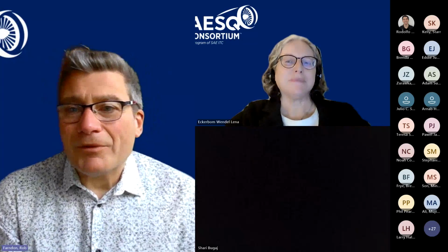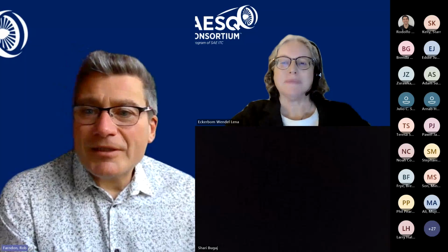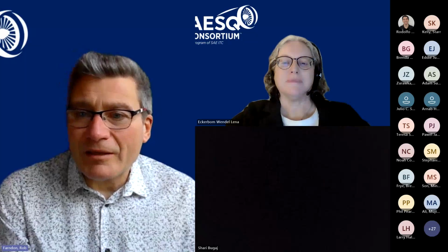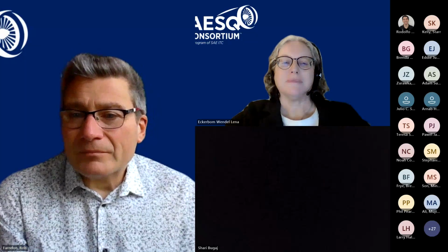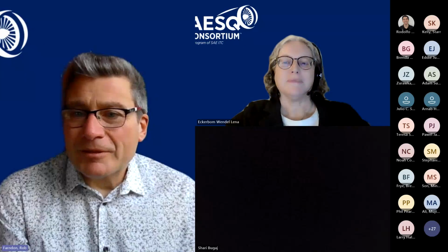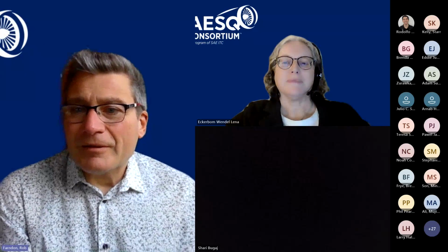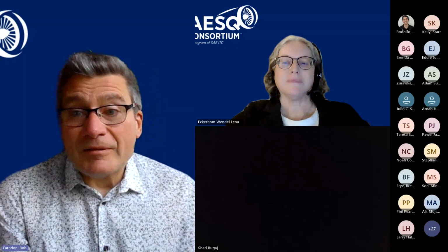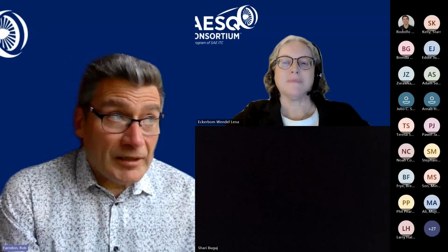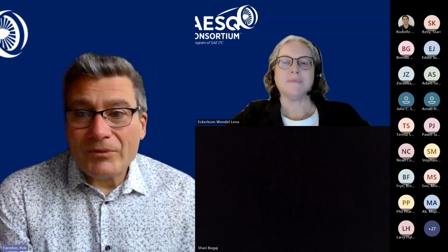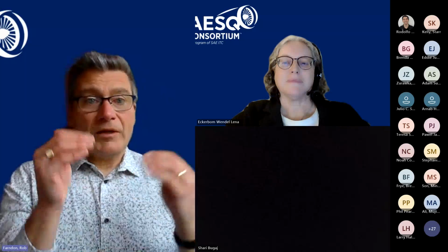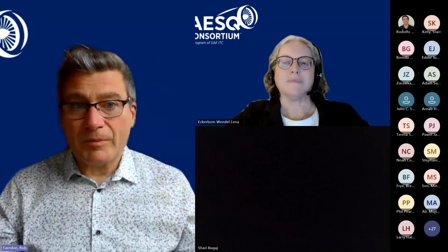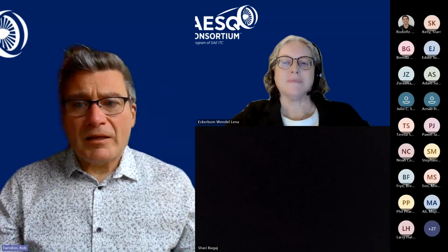Okay. There is another question come in, which is, can you go into a little more detail about how FMECA evaluates safety compared to the rating scale FMEA assigns, based on expected outcome, loss of primary, secondary function, failure without warning, etc.? Well, I think the thing we would say is that the numbers are not unrelated, but they are different. The severities might well have a close relationship with each other. You're thinking about what the impact of a particular failure might be. The occurrence, though, is very different.